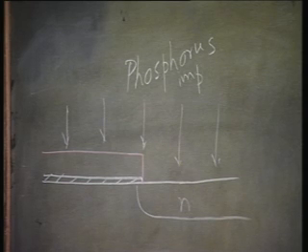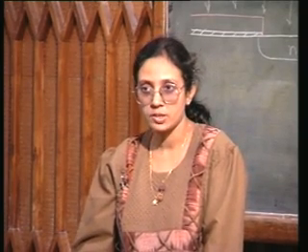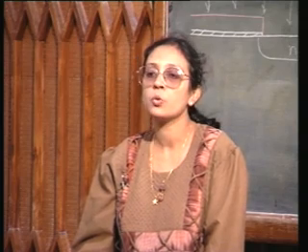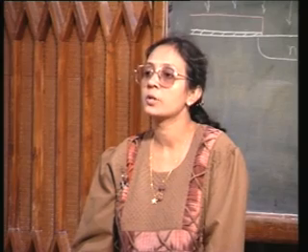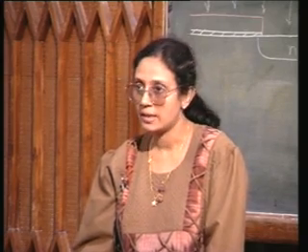Now you carry out an oxidation over the Nwell. I mean, you subject the entire substrate to an oxidation process. The oxide is going to be formed only over the Nwell because the rest of the portions are protected by the oxide nitride mask.